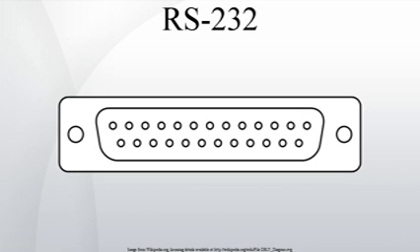This type of connector became the de facto standard for PCs and as well for many other DTE devices. Presence of a 25-pin D-sub connector does not necessarily indicate an RS-232C compliant interface. For example, on the original IBM PC, a male D-sub was an RS-232C DTE port, with a non-standard current loop interface on reserved pins, but the female D-sub connector on the same PC model was used for the parallel Centronics printer port. Some personal computers put non-standard voltages or signals on some pins of their serial ports.